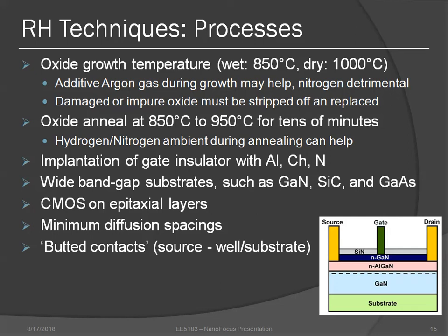And then looking further, wide bandgap materials, those are the materials defined as having small atoms with strong electronegative atomic bonds, can give higher tolerance to deep level defects. Some examples of these are gallium nitride, GaN, silicon carbide, and gallium arsenide. So, for example, with GaN-FET, there's no oxide layer, so they're inherently hardened against total ionizing dose, so they don't have any place to trap that positive charge.